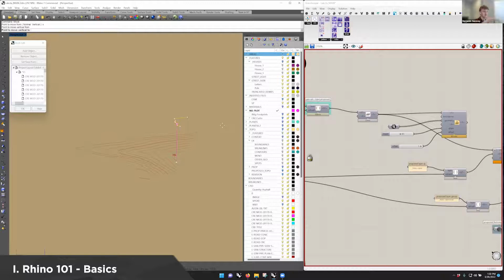If you move one contour up and then want to move all the others at once, you can move them up all simultaneously to the same plane. By the way, V is actually a shortcut command that we have, Ben, that not everybody has. The longer version is you just type M for move and return, and then V return to get the vertical. It's just a slight tweak to that. Yeah. Cool.